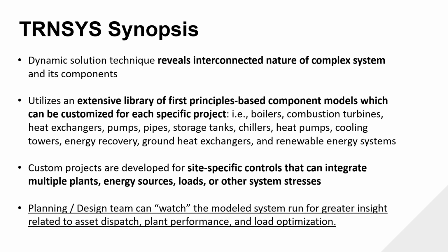But at Princeton's tire plant that we designed using Transys, they thought they needed another 1,000 boreholes on that campus. We went in and ran 3 different dispatch models and showed them you could skip the 1,000 boreholes and just dispatch your thermal storage tanks differently, and it saved them approximately $80 million. So they were fairly happy with that output from Transys, rather than putting in all these boreholes.